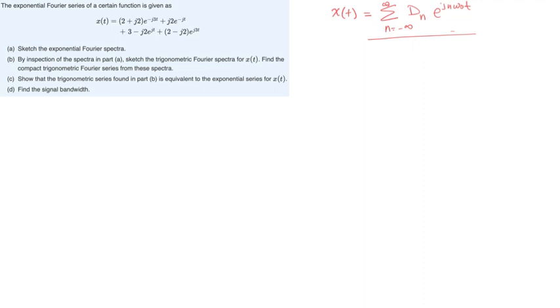By the way, when we say the lowest frequency, we only talk about the positive. Okay, so whenever I ask you, for example, what's the lowest frequency of a signal, don't tell me it's -3. It's always the positive side. The negative side is just an expression of mathematical completeness or mathematical correctness. But there is no such thing as a frequency of -1 or a frequency of -3. Okay, so anyways, the lowest frequency that we have here is 1.